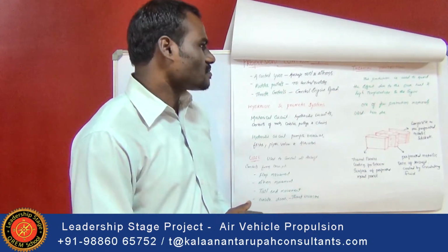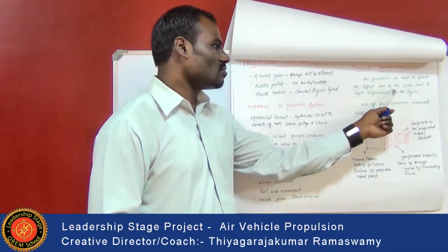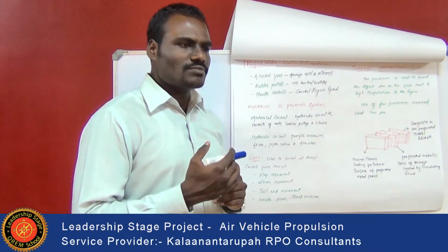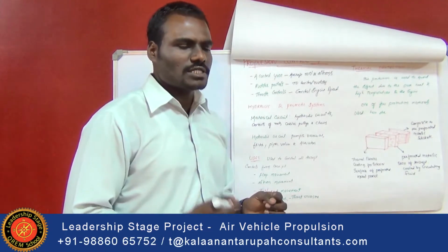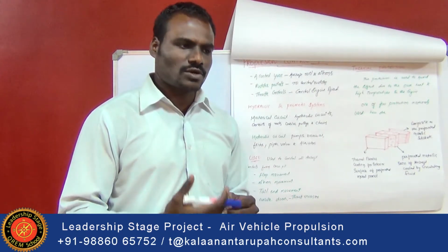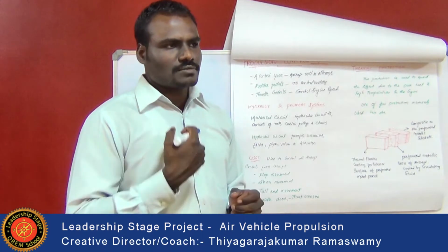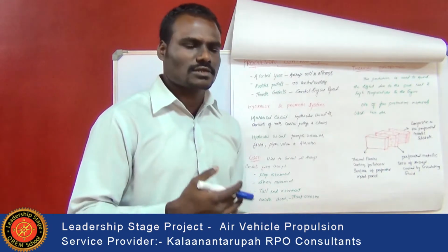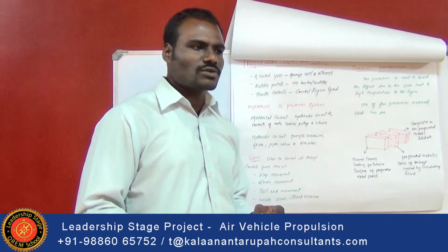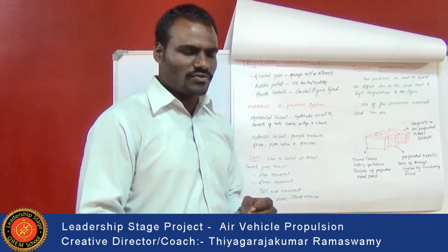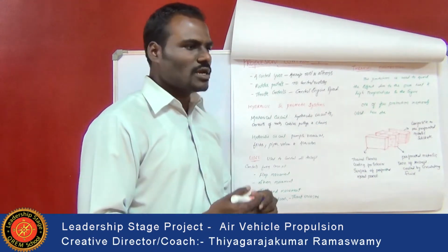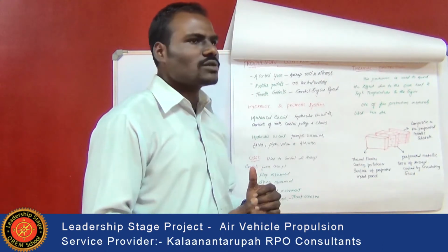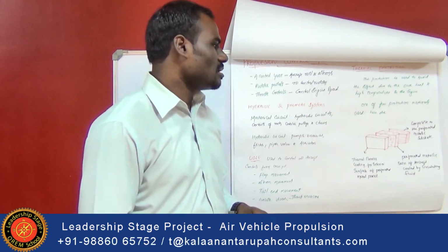is studied under the thermal protection system. This protection is used to avoid the effects of overheating and high temperature in the engine. Here at the combustion chamber, the air which is subjected to the combustion chamber is burned at very high temperature, so this temperature should not affect the other parts and the nacelle structure. The temperature is to be maintained in a way that it should not affect the external parts of the nacelle structure or the engine, which leads to a reduction of efficiency. So major work is carried out in the thermal protection as well.